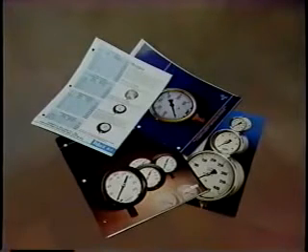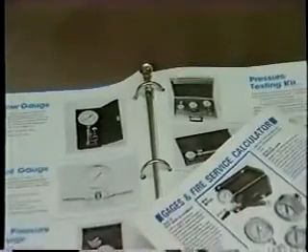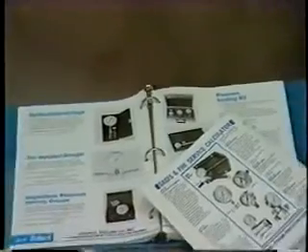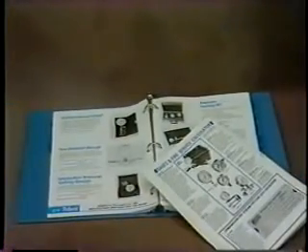The things you need to run the test are pressure gauges. You can buy the necessary gauges and hydrant cap fittings from any fire equipment or pipeline supply company. Some companies even sell complete kits with everything you need to run the tests. Usually, however, when you buy these pieces of equipment, you get some fairly inexpensive gauges which are not really all that useful if you want to get some very accurate tests. This one, for example, is graded every 20 psi, and you have to interpolate between those. Of course, this doesn't give you very good precision or accuracy.